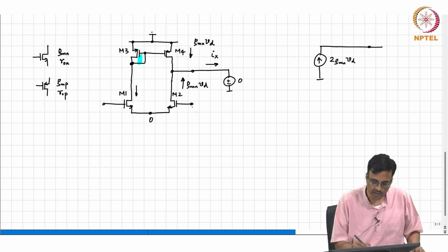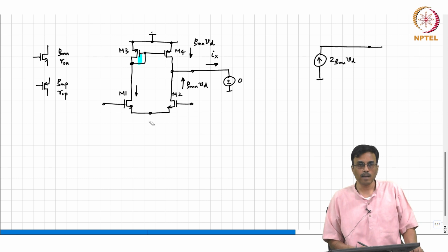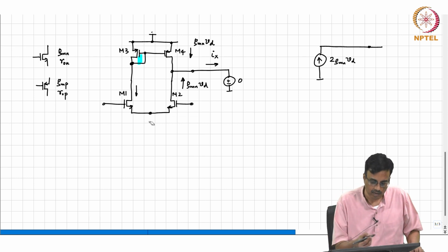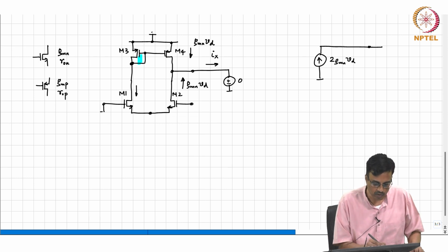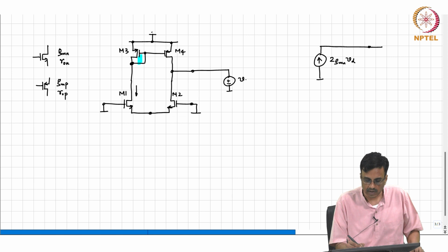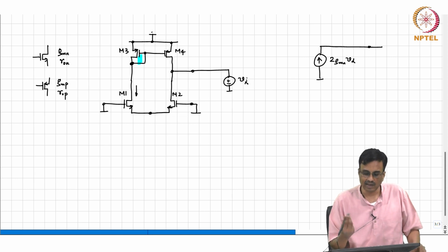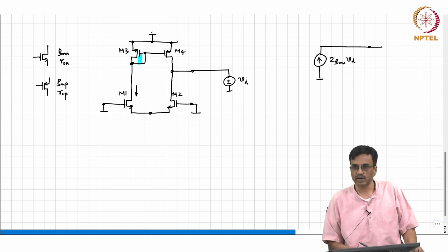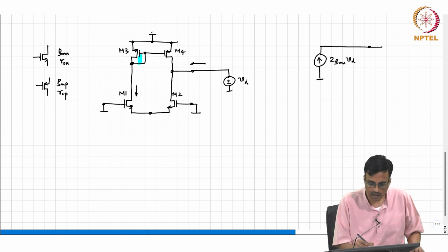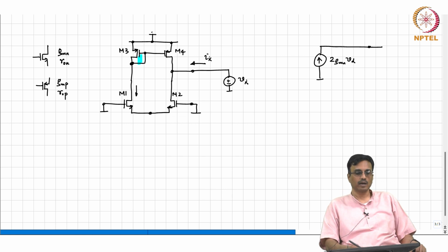All right. Okay, now is the hard part, which is, what is the output resistance? To find the output resistance, what do we do? We remove both the independent sources. So, this is ground, this is ground. Okay, so what should we do here? We apply Vx, I do not want to write test, I will just call it Vx, and measure this Ix.